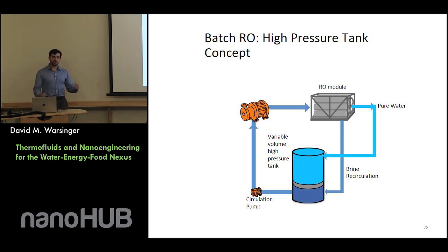So in the batch process, we had a very large volumetric flow rate of brine that was leaving the system, and that had a very large energy loss associated with it. So we needed to have expensive turbines to recover that energy. However, in a closed system, if you had a volume of incompressible fluid, which is water, essentially incompressible, you compressed it really high, and then you depressurized it, right? Your PdV work, when dV is essentially zero, approaches zero. So you have nearly no energy losses when you depressurize this system. So you can do this without actually needing these high pressure energy recovery devices.